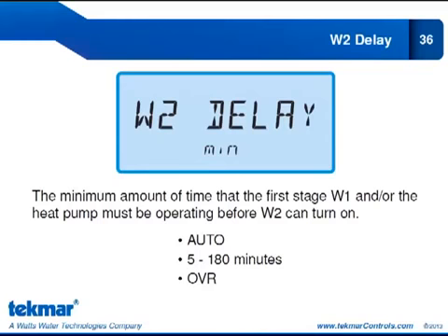So emergency mode is when your heat pump is not operating. This W2 delay is not applied when the heat pump is locked out. It's not applied when W2 is the only stage available for heating. And it's not applied if the heat pump is turned off in respect of the balance point. So it won't hold off W2 in cases where we need W2.